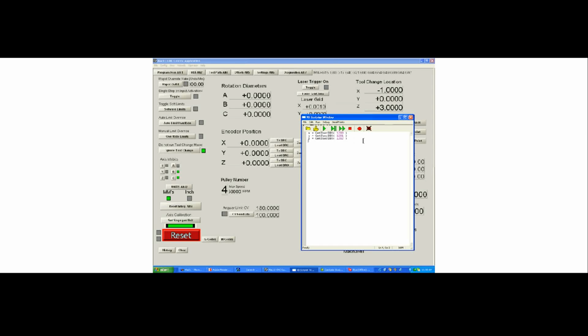So let's say that on a tool change, you want your tool to go to a specific coordinate, which will always be remembered in those tool change locations. We can do that by typing code and a quote, and now whatever we put in this statement will be executed as if it's normal G code. Since a tool change location is usually in machine coordinates, you would not want to use a G1 or a G0 to go there. You would want to use a G53, telling the system to go to a particular machine coordinate. So let's use a G53, G0.